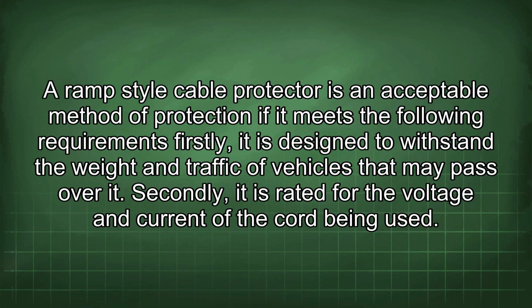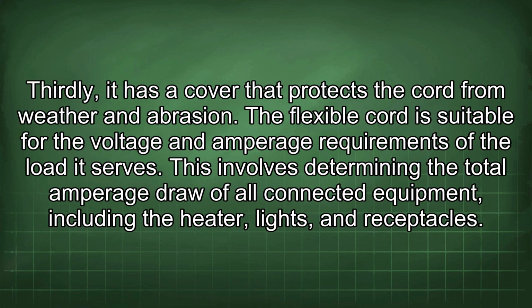A ramp-style cable protector is an acceptable method of protection if it meets the following requirements. Firstly, it is designed to withstand the weight and traffic of vehicles that may pass over it. Secondly, it is rated for the voltage and current of the cord being used. Thirdly, it has a cover that protects the cord from weather and abrasion.